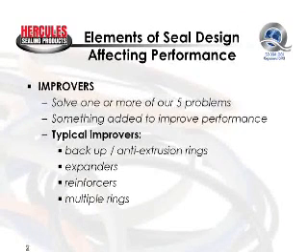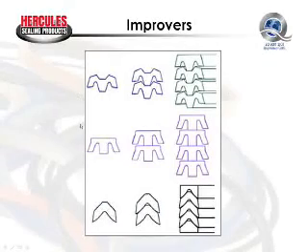Okay, and there's various types of V-packings, multiple lip seals. Here we see non-gland sensitive multiple lip seals. And these are non-gland sensitive because by squeezing these seals axially, they have no effect on the radial flare of the lips. The radial flare of the lip is designed into the seal, and they cannot be adjusted by squeezing on them because of the center leg down through the center of it. Here's a different type of non-gland sensitive ring, and again, no adjustment on the lips of the seals.